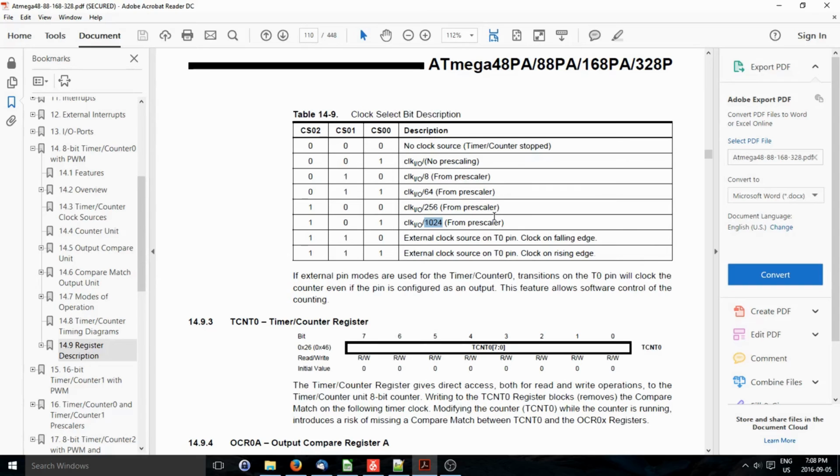It slows down the 16 megahertz oscillator to a level that we can generate a count within 200, which is less than 255, the maximum value of the timer counter register. And then these two modes just determine what the signal on the timer 0 pin is.